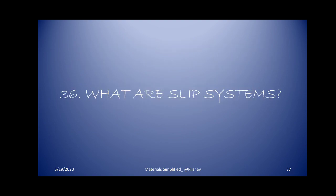Moving on, what are slip systems? Dislocations move in certain crystallographic planes and in certain crystallographic directions. This combination of slip planes and slip directions is known as slip systems. Dislocation cannot move in any plane. Dislocation can only move in close-packed planes.